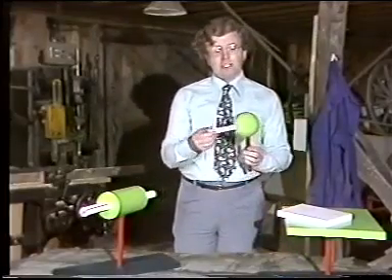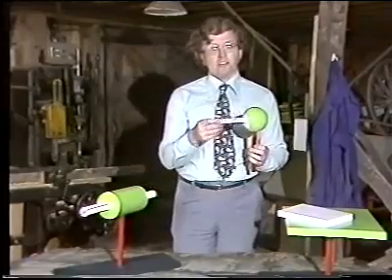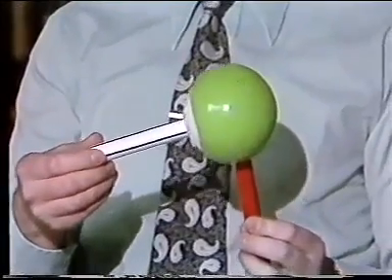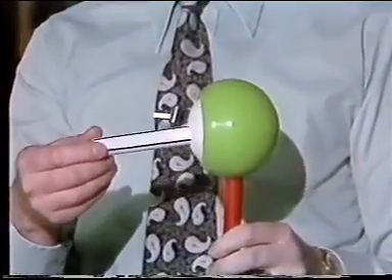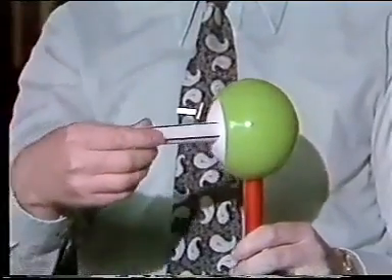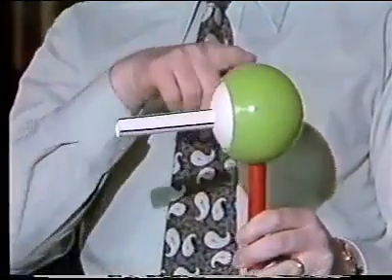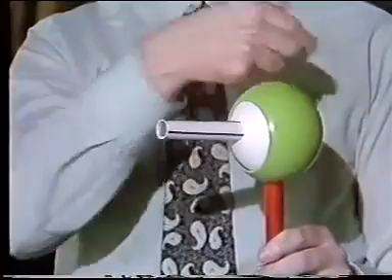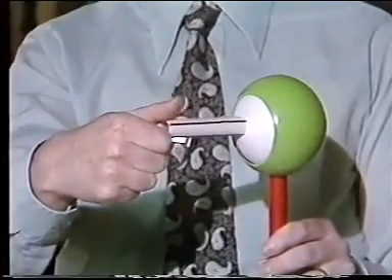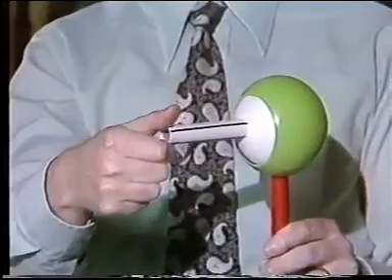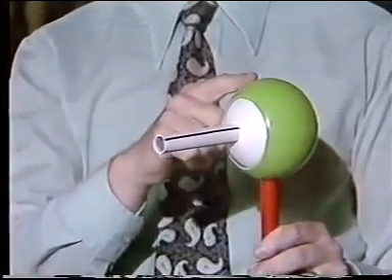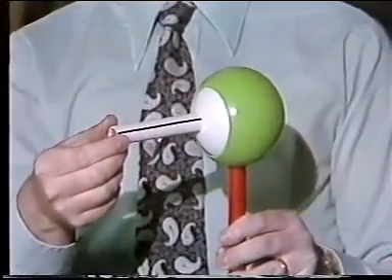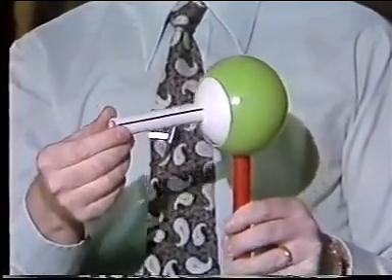Now, here's a familiar-looking joint. You probably know it as a ball and socket, the sort of thing you have on a car mirror. But in Reuleaux's terminology, it's known as a spherical pair. And this joint allows 3 different rotations. One about a vertical axis, like this. One about a horizontal axis this way, that's like that. And the other about the other horizontal axis, like this. So we've got to specify 3 parameters to give the position of one link relative to the other, 1 parameter for each of those 3 rotations. And the spherical pair, therefore, has 3 degrees of freedom.